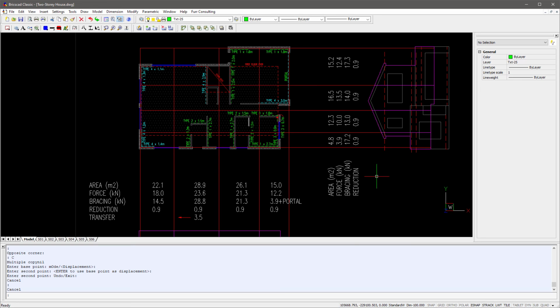Under a situation like this, it may be possible to meet our design forces for each area, but then all the bracing ends up in one end. This goes against the idea of evenly distributed bracing throughout, and so to address this, we have upped the corner bracing here to type 4 to ensure we'll have appropriate bracing capacity at this face. With that complete, we now have our standard bracing complete for both levels, with our one brace frame to deal with later on in the design.